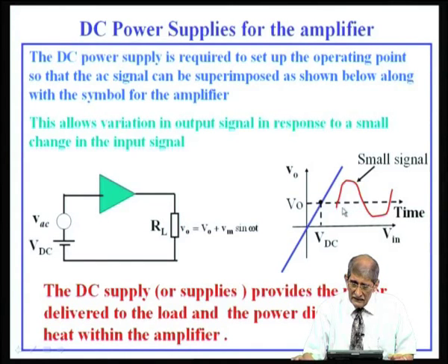So, now you can see that you can superimpose this, you can analyze DC and AC separately, you can separate out DC and AC. If you put a capacitor, the DC will be blocked, you can get only the signal. If I have a signal here, I can get only the signal here, removing the DC by coupling a capacitor here and taking the voltage at the output.